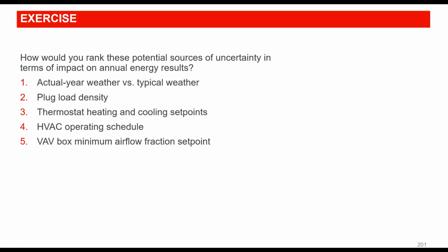And then last, Jose asks, is BIM modeling capable to use in industry to account for all inputs and outputs that are described so far? So BIM is more of a tool for doing the three-dimensional description of the building. And one of the problems I personally have with building information modeling is many of the BIM models I see don't have a lot of detail. They may not have the thermophysical properties you need, and so that can be a challenge.